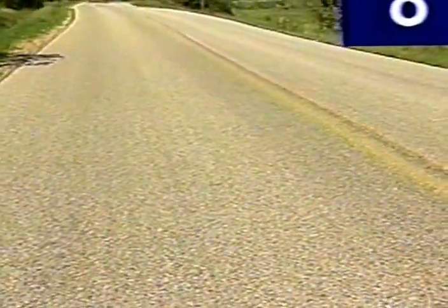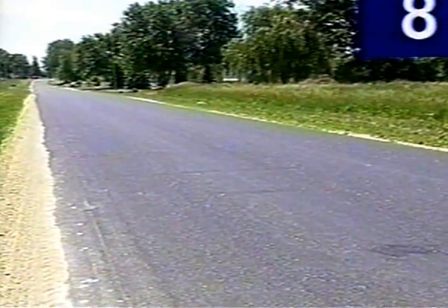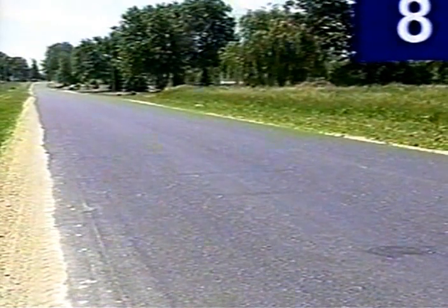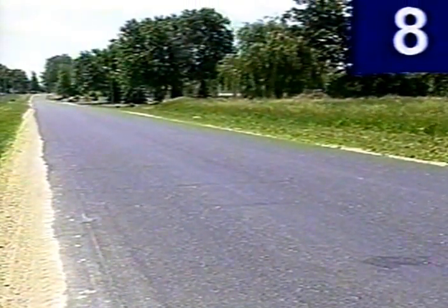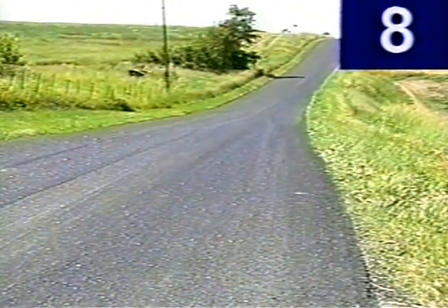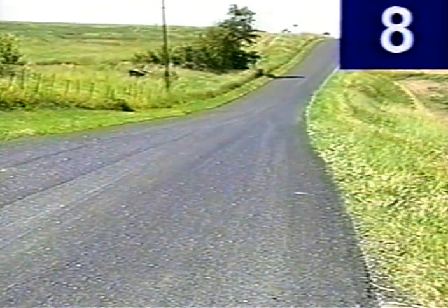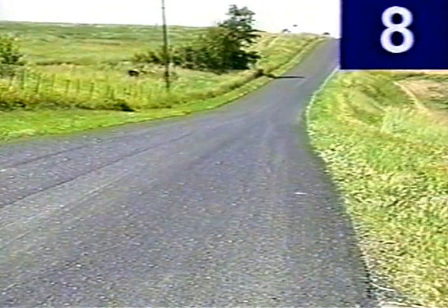If we next move to pavements that are rated an 8, we're talking about roadways that have had a recent seal coat. Here's an example of a brand new chip seal in very good condition. Here's an example of a pavement that's had a slurry seal. It's in very good condition and therefore would be rated an 8. An example of another field application of a surface treatment. This is a seal coat that's used a black slag aggregate. Pavement's in very good condition, requires nothing to be done, would be rated an 8.